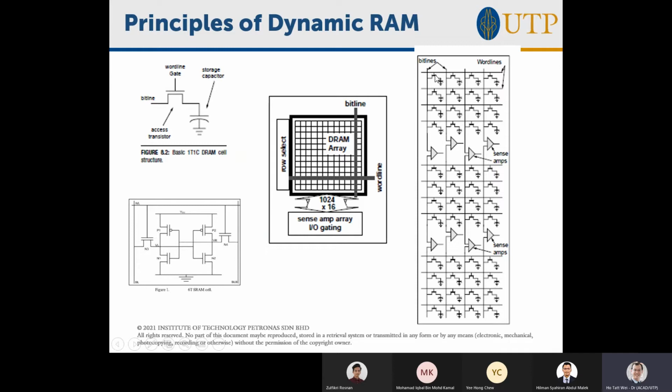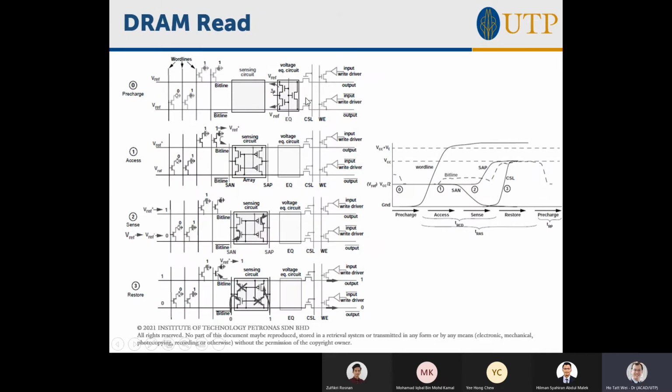But when I choose the word line, I'm actually doing this same process for all the bits on the word line. It's all the bits on the row, happening at the same time. I'm just showing you here the circuit for only 1 bit. So what happens on this bit line? The word line is selected for this particular transistor, this particular bit. This one is not selected, this one is not selected, this one is not selected. So it's going to read out this cell.